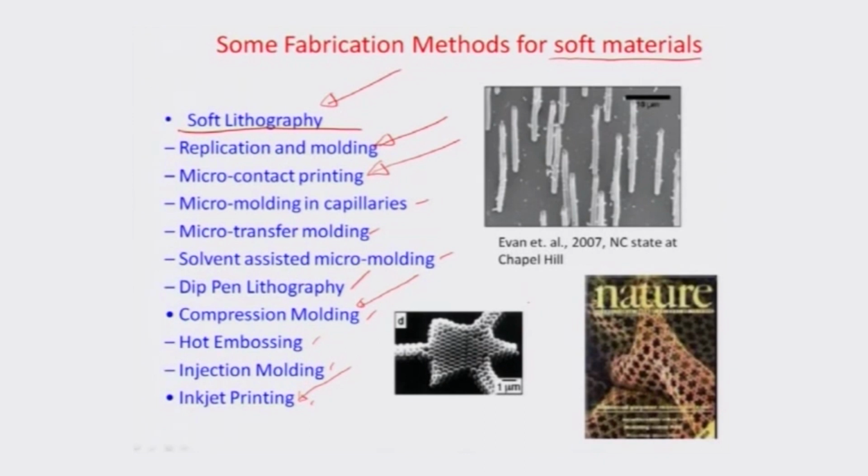These are some examples of what can be done with polymer MEMS. For example, this is an illustration of how PDMS doped with Fe2O3 particles can be used to make these high aspect ratio structures. These structures must be close to 20-30 microns high and maybe about 2 microns in diameter, and these can be used as tentacles. Just because they have Fe2O3, an external magnetic field tends to move them, and they can be used for pedaling action, which can move forward the organism that possesses these tentacles.